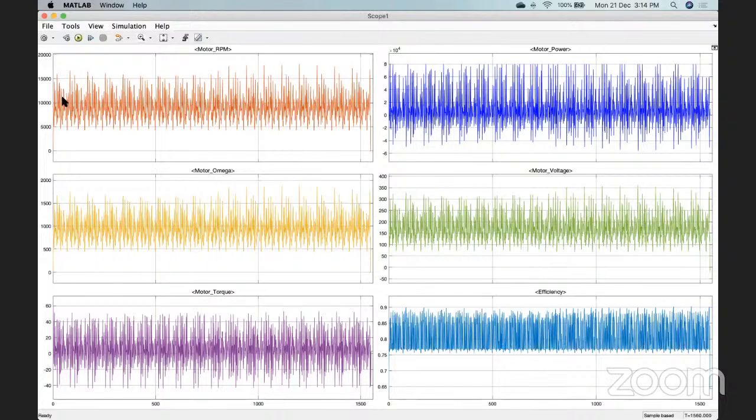And if you look over here, you can find out the nominal RPM values also. Okay, so based on that you can tell your vendor, so this is my requirement: 18,000 RPM is my peak RPM of the motor, and the nominal value is somewhere around 12,000 or 10,000 RPM, and the torque value is coming somewhere around 60 Newton meter approximately. That is the peak torque, and the nominal torque will be somewhere around 30 Newton meter or 28 Newton meter, something like that.